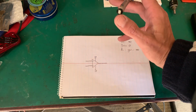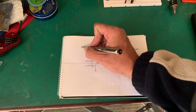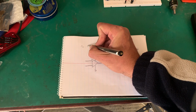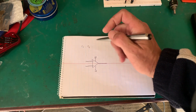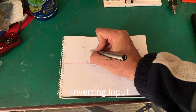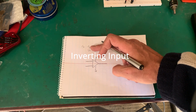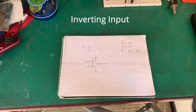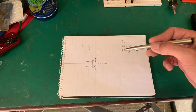All it means is if I'm using the non-inverting input, whatever is happening on the input, the same thing is happening on the output, albeit, depending how we configure it, with a bit of gain. The inverting input will be the opposite. It will be out of phase. So in phase, non-inverting; out of phase, inverting. Very simple. Two new terms to add to your arsenal, actually four.